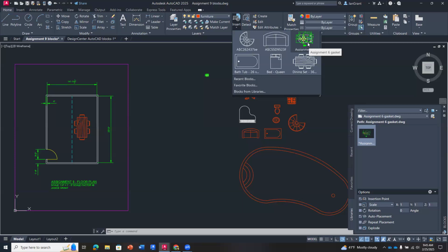And you're finding out that when you insert one file into another, the whole block goes on the current layer. It also creates a block inside the file so that you can go get it later on and not have to navigate through all of that. And it's a great way to not have to draw something over again.